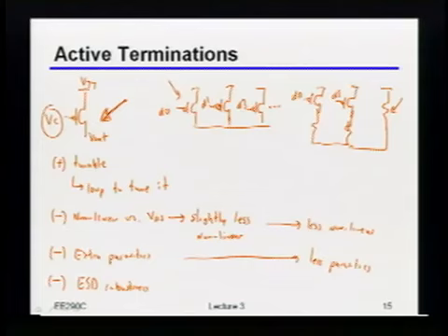That's all. It also depends on exactly how it's sized. It does also slightly isolate you from the parasitics of those caps. In other words, it creates a zero in the response that, if that zero is at a nice enough point, then you'll actually be somewhat isolated from the additional cap there. Obviously, it depends on how exactly you've sized the thing, but that's the first order answer.